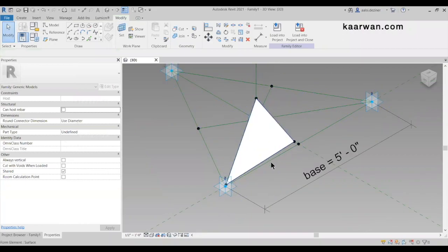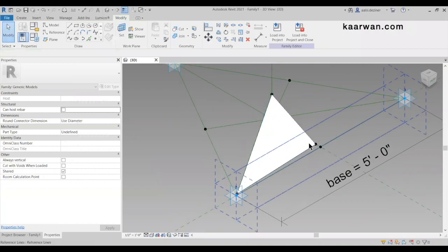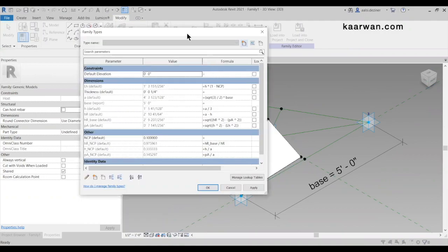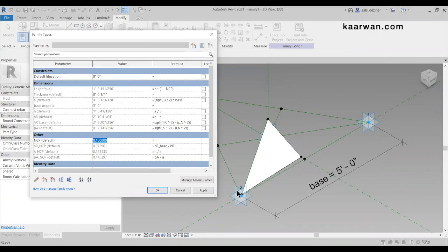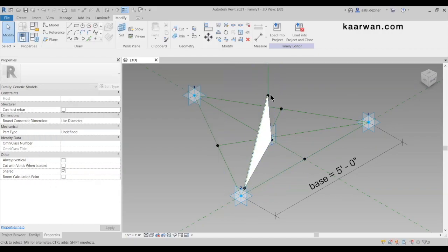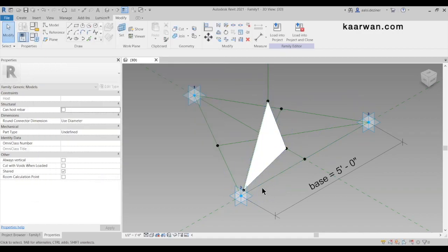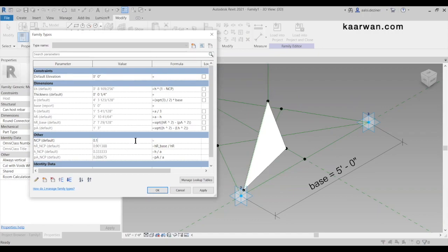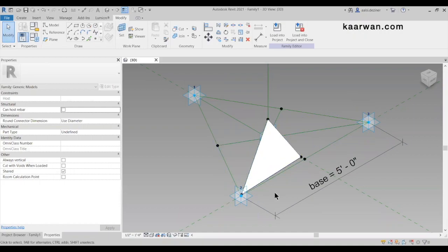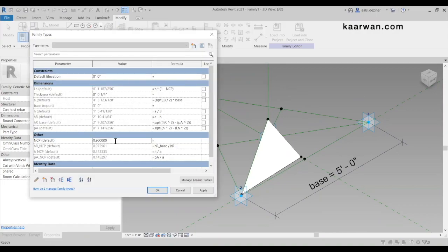This is how your panel will be looking, part of that will be. So you should be able to flex this and check that the curtain panel is adapting accordingly. So as you change the NCP value, the control point value, which is the only editable parameter here, as this value changes, you should be able to see how the part of the panel opens and closes. Okay, that is 0.5. Then it partially opens. And if you reduce it, bring it closer to 0, then it fully closes. Okay, so the panel is covered when it's closer to 0, and the panel opens, revealing the data as the value gets closer to 1.